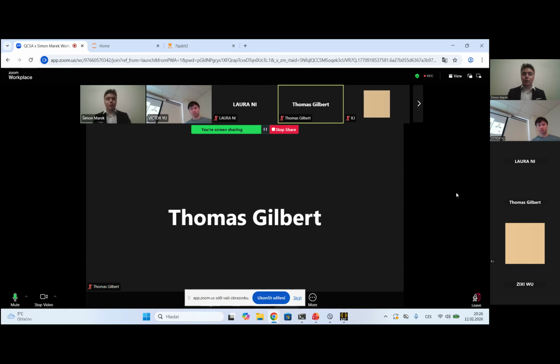Then you need to import it to Blender, and from this, you need to define your materials. You need to create some plane for the renderer, and then you need to set up lighting. You need to set up a camera, and then you can do realistic renders like this. Okay, awesome. Thank you. No worries.